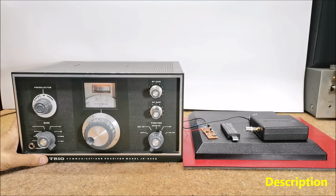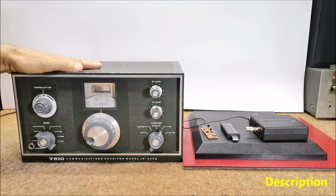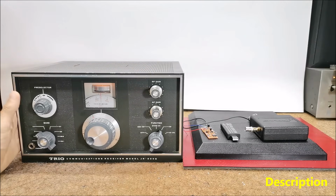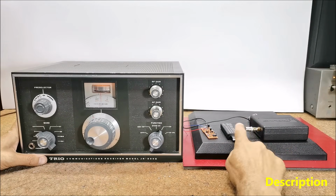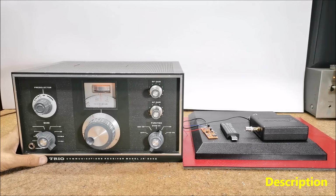or unused frequencies. There are generally two types of Panadapters: hardware-based, dedicated external devices that connect to a radio's IF output, and software-based Panadapters that use SDR receivers like RTL-SDR, SDRplay, or KiwiSDR to display spectrum data on a computer monitor.